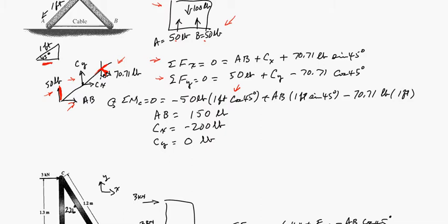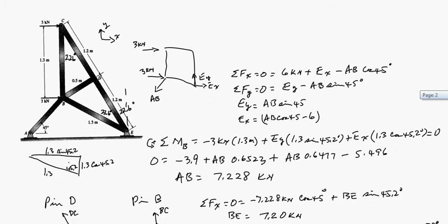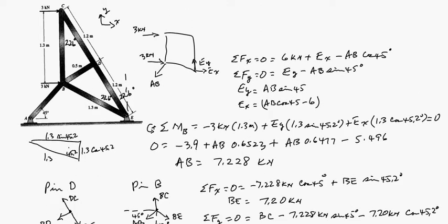That's the nature of that interaction. So that force times distance simply ends up being the 70 times the distance from here to here. Oh, sorry, we're summing the moments about C. From here to here, that ends up being 1 foot. And solve the algebra.